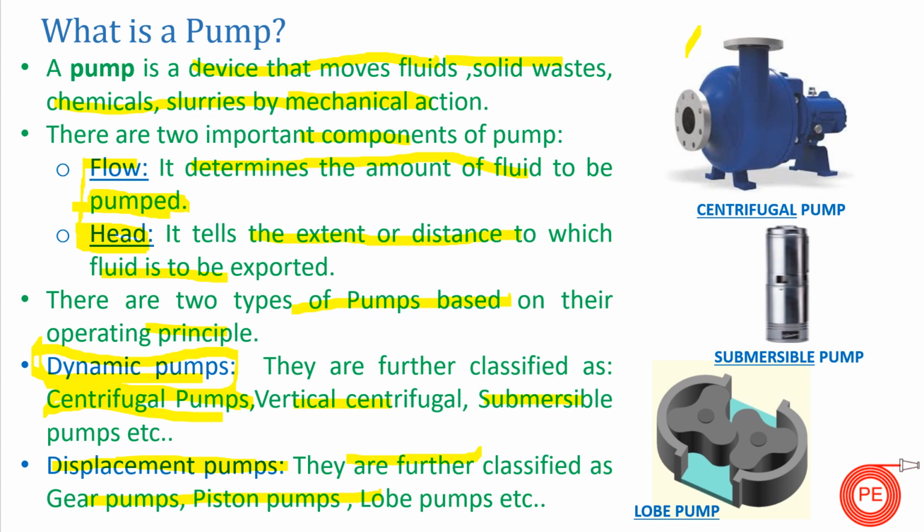The pump shown here is your centrifugal pump. There are two types of centrifugal pump. One has a front suction and top discharge, and the other has a side suction, and parallel to this suction there is a side discharge in the pump.